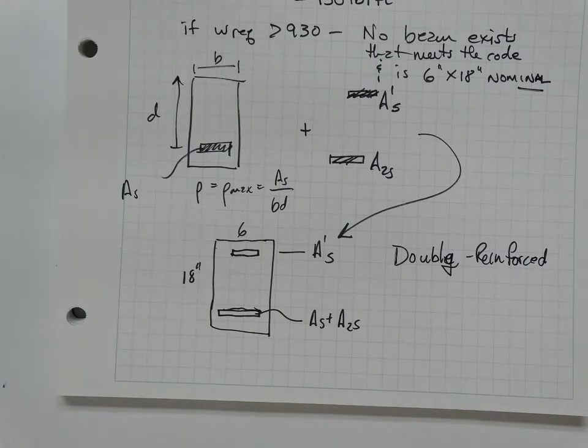constant. They may give me a compressive strain, give me a tensile strain. It doesn't matter. Up until the yield point, till the yield stress, I'm elastic. After that, I'll yield. And I'll yield in compression, and I'll yield in tension. Tension's easier for us to imagine, but the steel will yield in compression the same way. That's what we're going to do over the next several, at least 2 weeks. We're going to learn how to analyze doubly reinforced beams.